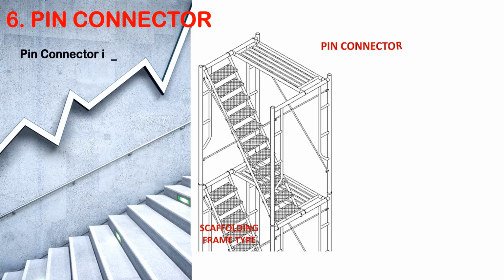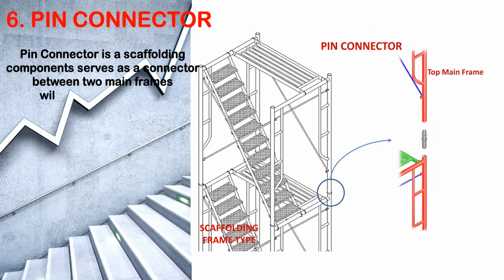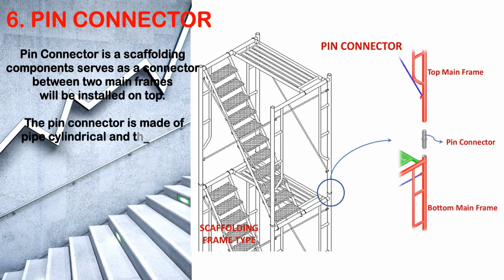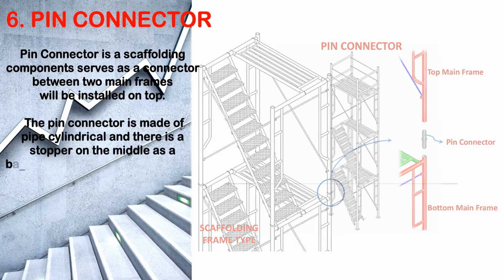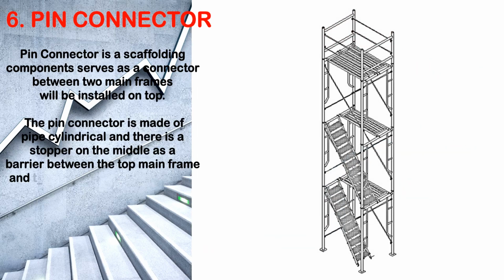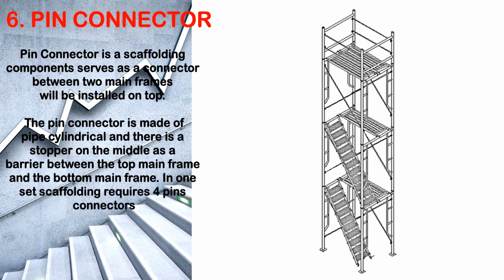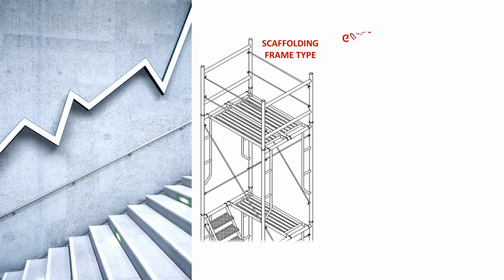Number 6. Pin connector. Pin connector is a scaffolding component that serves as a connector between two mainframes that will be installed on top. The pin connector is made of cylindrical pipe and there is a stopper in the middle as a bearing between the top mainframe and the bottom mainframe. One such scaffolding requires 4 pin connectors.